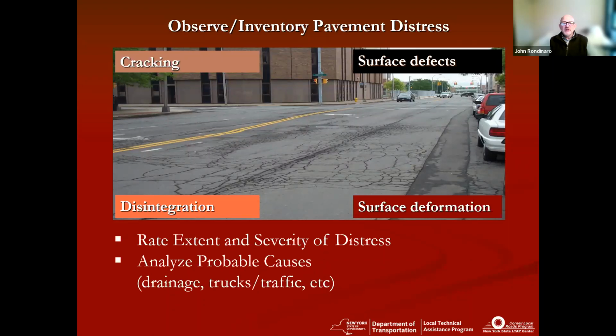You've got to look at your underlying soils. They can be a big problem to deal with, underlying utilities and drainage structures. And then you've also got any kind of construction issues, design issues, or maintenance issues that may be causing problems with your pavement.